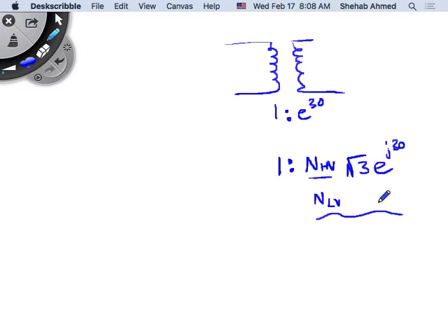So that's a summary of what we discussed last time. Any questions on that? Of course the impedance transformation from primary to secondary still applies, and you do not change the angle of the impedance. Since it's a one-to-one ratio from a magnitude perspective, from a per unit perspective the impedance in the primary is equal to the impedance in the secondary. Nothing changes. Voltage and current magnitudes also don't change in per unit. What changes is the angle.